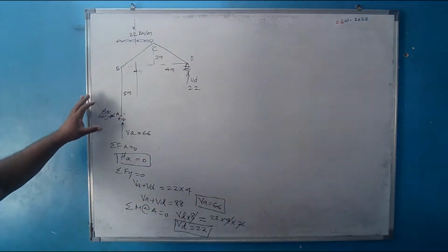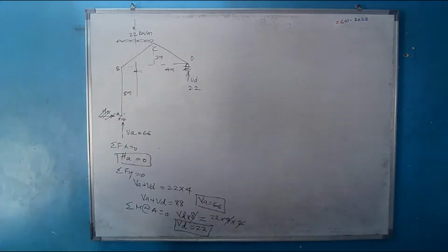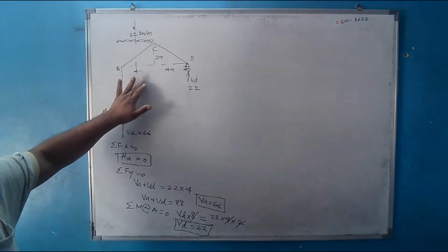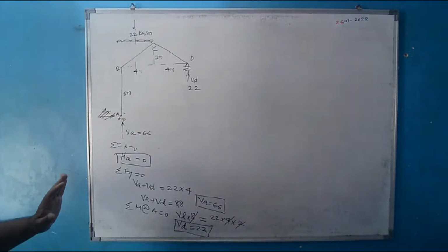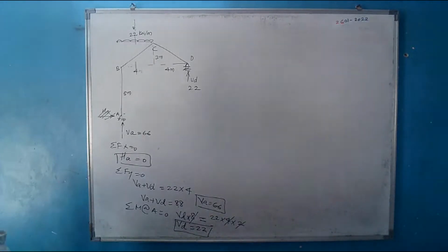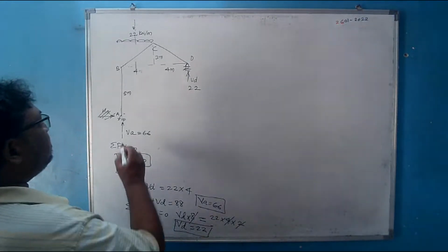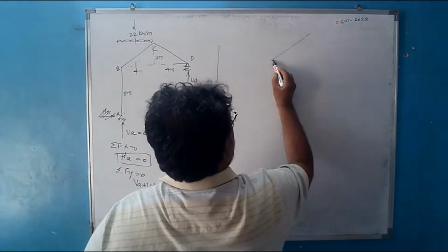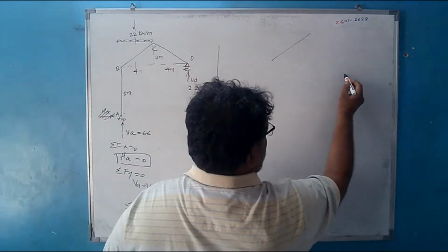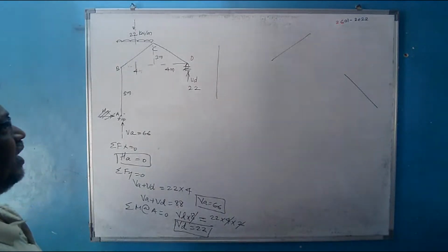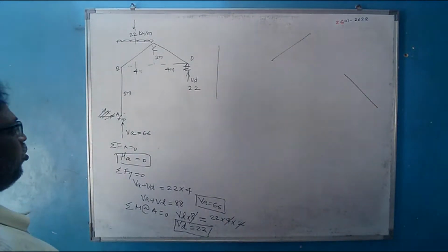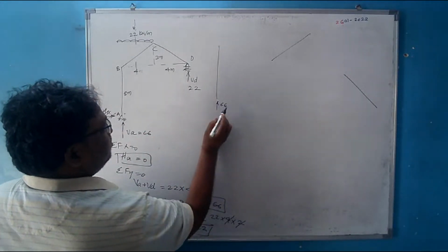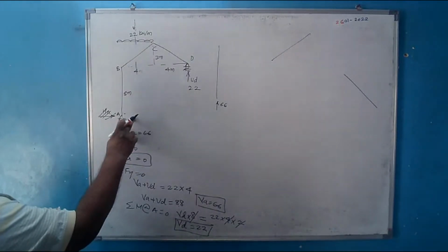After getting the reactions, after getting the unknowns for the supports, after solving the problem for the external equilibrium, now you break the element into a number of components. How can this be broken into components? First, a vertical component. Second is this inclined component. And third is this inclined component. Is it right? We are breaking these into components. This VA is 66. There is no horizontal and there is no couple here.